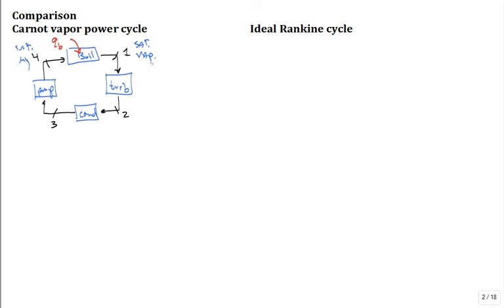Okay. Then when we expand it through the turbine, we're going to find, oh, we're in a 2-phase region. Oh, it's a relatively high quality, maybe 70-80% quality. And then we're going to condense it. We're not going to condense it all the way. Hence, we'll condense at the constant temperature and reject heat all at a low temperature TC, which is the saturation temperature at that condenser pressure. Just like we're bringing all this heat in at TH, that high temperature, the saturation temperature at the boiler pressure.